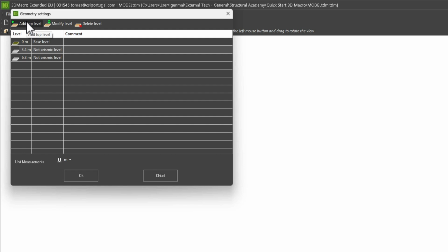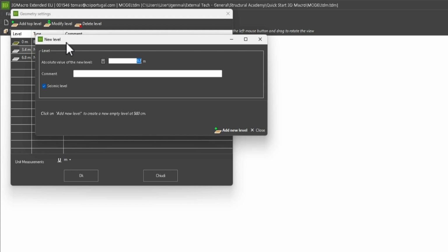Elevations to which no significant amount of mass is associated can be defined as non-seismic, for example, elevations at stair landings, elevations on parapets at the top of buildings, etc. Seismic elevations are those associated with a significant amount of mass, usually for example at the floor levels.